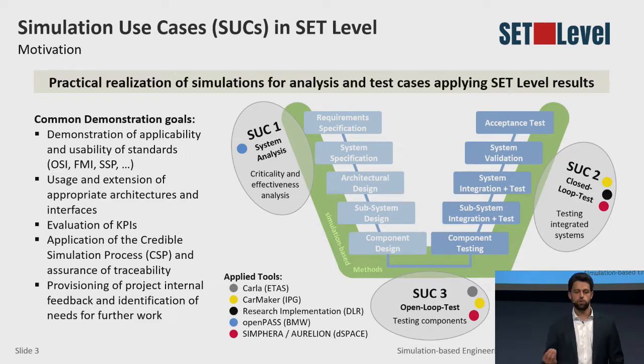So this could be a great input for simulation use case 2, where it comes to the test of an automated driving function. In our case, this was done in a closed-loop simulation, focusing on the test of this integrated system composed from multiple individual components. And as a third simulation use case, we decided to go more into the details. So we kept the simulation quite small. It's a component test, a single component that is the system under test, but it is simulated in great detail. And we will see what that means based on the examples for camera, radar, and LiDAR sensors.